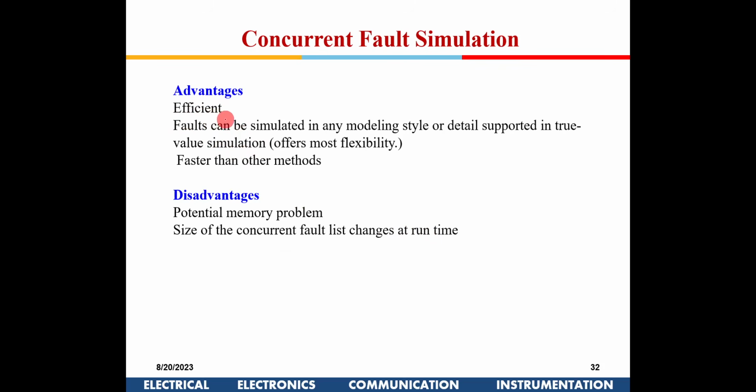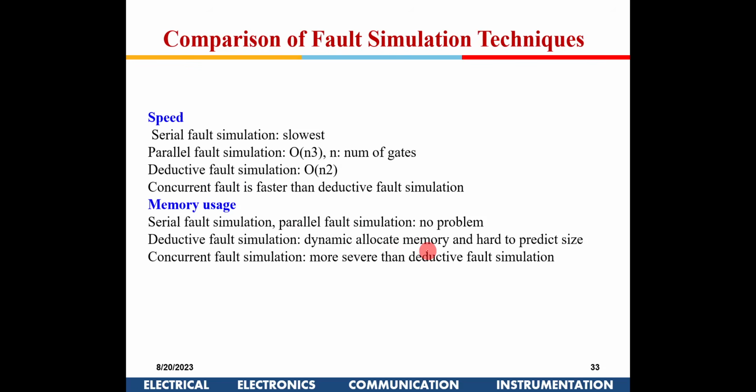So the advantages: it is efficient, faults can be simulated in any modeling style, and it is faster than other methods. Again, it requires more memory, right? The size of the concurrent fault list changes with runtime. These are the disadvantages.